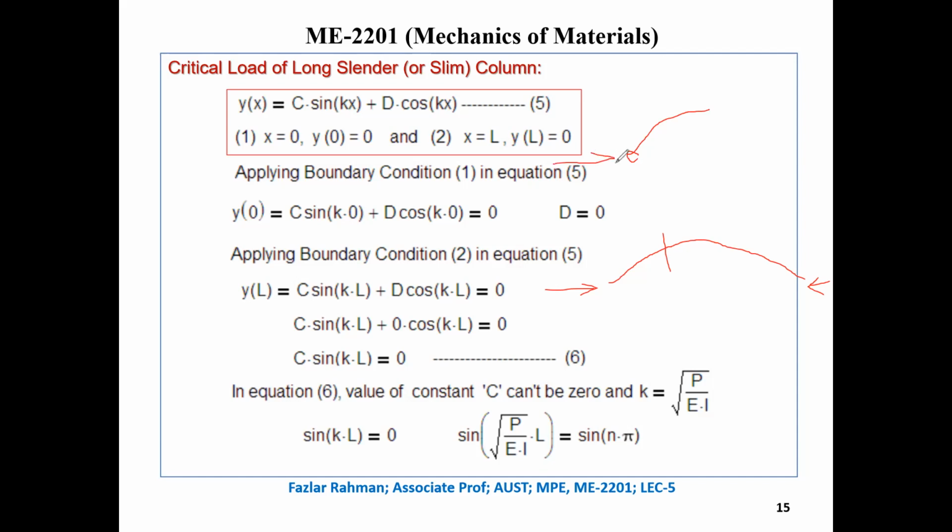Load you apply externally, right? Now, I would like to figure out the force right at this point. By how? By applying your rule from your statics. Summation of Fx, Fy, and summation of moment will be 0. Because we are working with a static body, not a dynamic one.